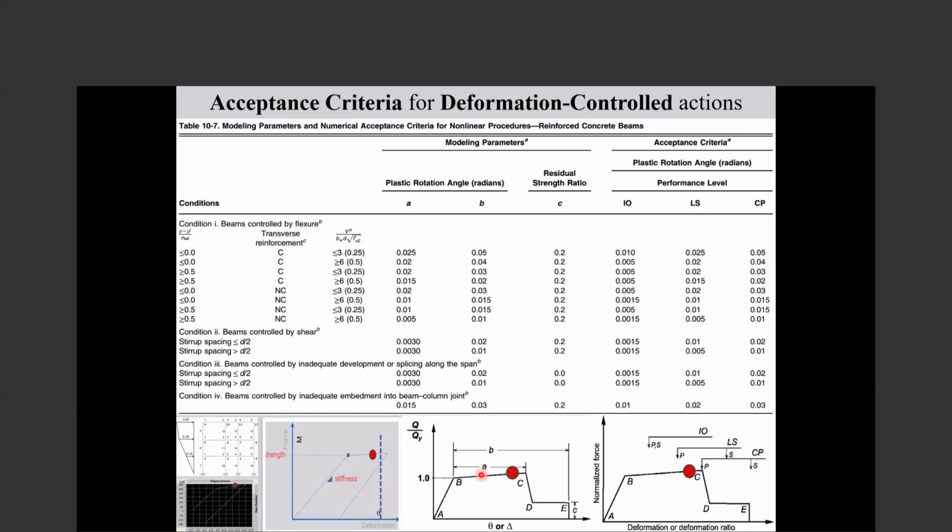But anyhow, if the results were approved by nonlinear analysis and you come and check with linear, and it is 20% more drift or 20% more, they ask you to satisfy the linear methods completely.